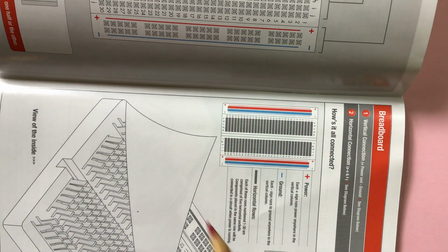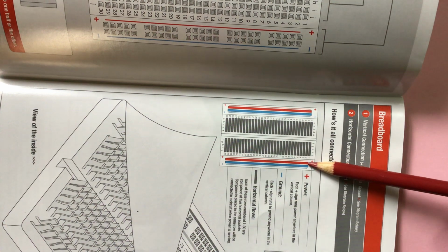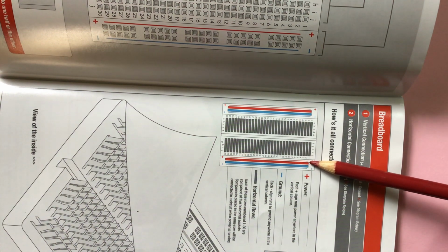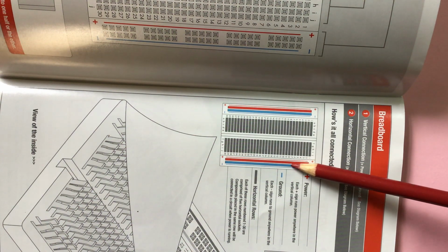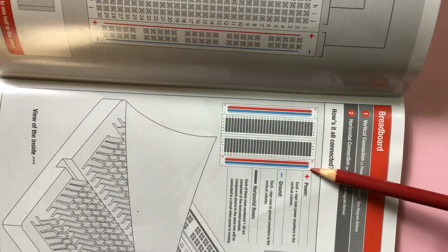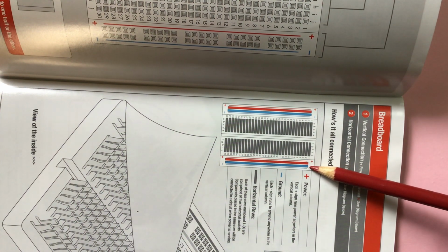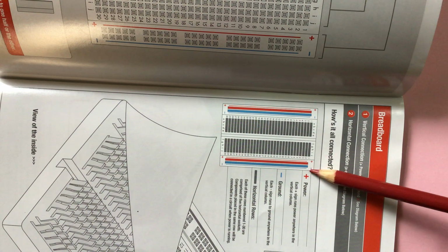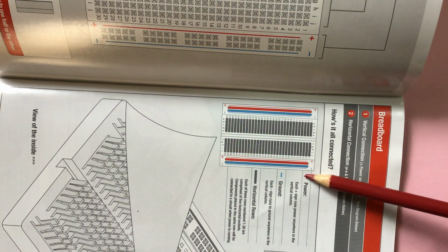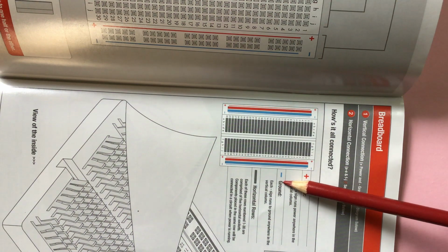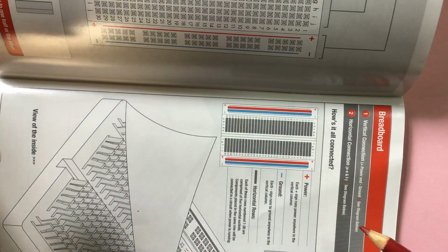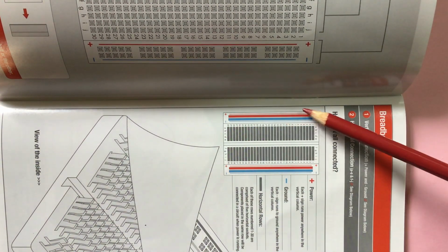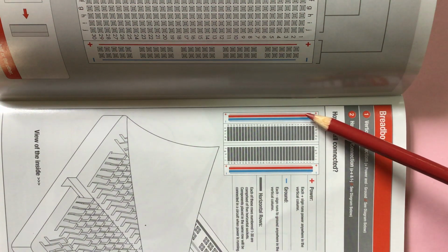So always it's good practice to connect the wire from the positive to this end, so that you will be tapping anything that needs power from the dots along this line. And at the far end, you will be connecting a black wire where there is minus. You'll be connecting there a black wire, and that black wire will be connected to the minus, to the negative. The negative in electronics, we also call it ground, as you can see there. So now that this side is the same as this side, they are connected horizontally. Anything connected there will be able to tap power.